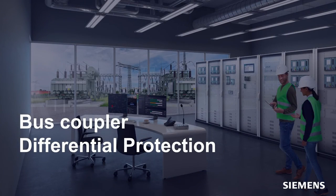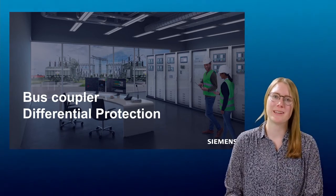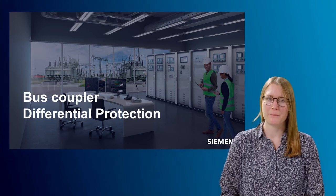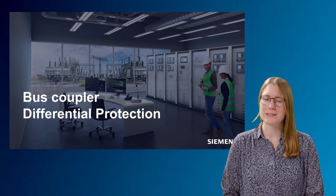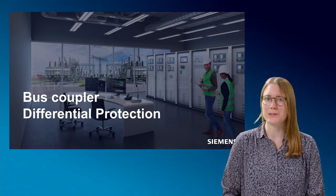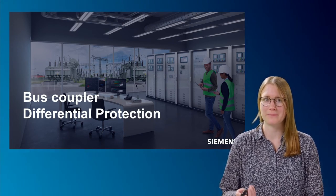Yeah, so this is all I wanted to explain about end fault protection. Now I want to spend some minutes on bus coupler differential protection, because for a coupler with two CTs, in combination with end fault protection, it is a very good solution for a fault in the dead zone.